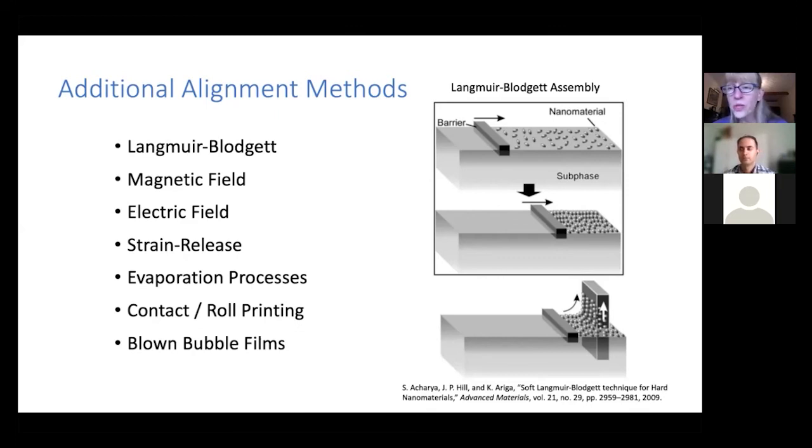Well, in the results that we showed, the gap distance is very close. It's just slightly larger than the average crystal diameter. So you can control that in this drawing process by controlling the outer diameter. Remember, the ratio of the gap width in the preform to the outer diameter is going to be preserved. So all you do is control the outer diameter, and the way you do that is by controlling the draw speed.